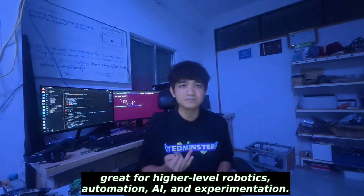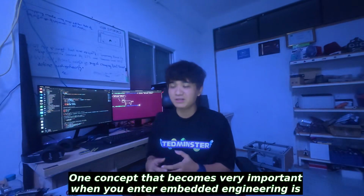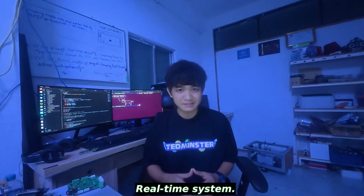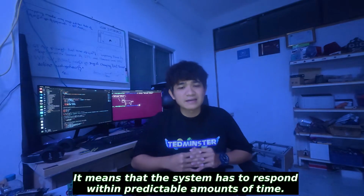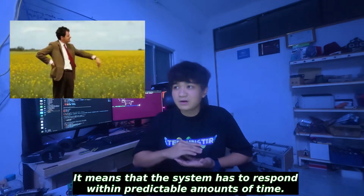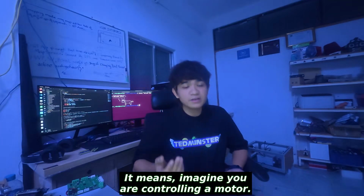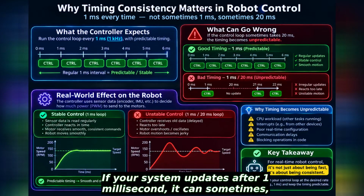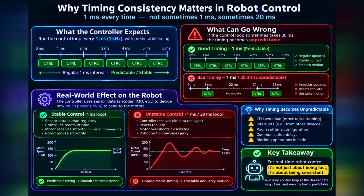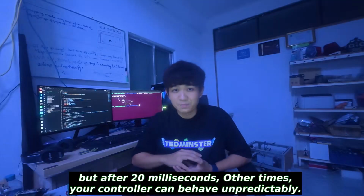automation, AI, and experimentation. One concept that becomes very important when you enter embedded engineering is real-time systems. Real-time doesn't necessarily mean very fast. It means that the system responds within predictable amounts of time. Imagine you are controlling a motor. You want to update your controller every 1 millisecond. If your system updates after 1 millisecond sometimes, but after 20 milliseconds other times, your controller can behave unpredictably.